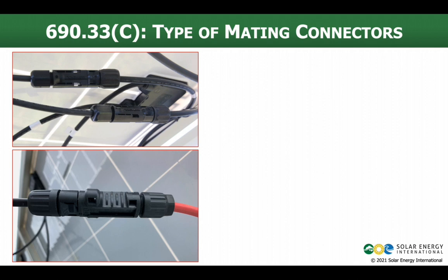Or maybe the little metal pins inside the connectors that actually make the electrical connection don't mate together well, even though the plastic body seems like it clicked into place really well. If they don't fit together well, there's more resistance. Again, more heat. So those are big issues, and we see so many connectors out there that we need to really have a handle on this and be sure that we are doing things right to minimize the hazard and the liability that you might then be exposed to.